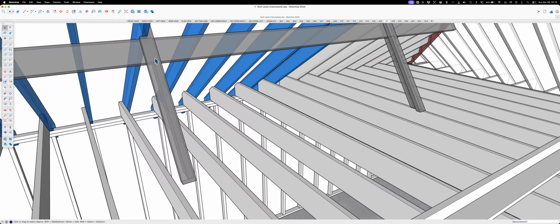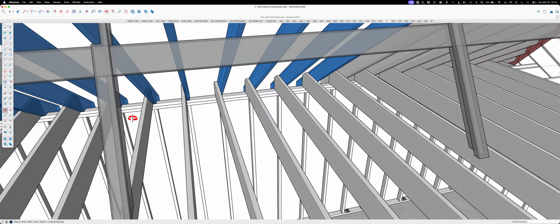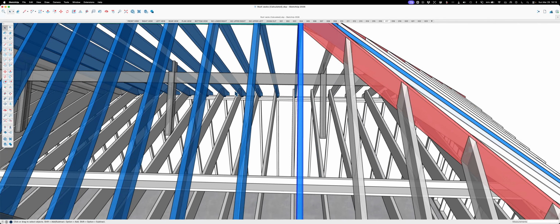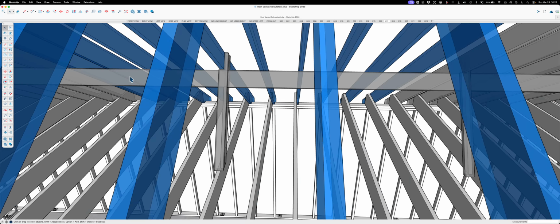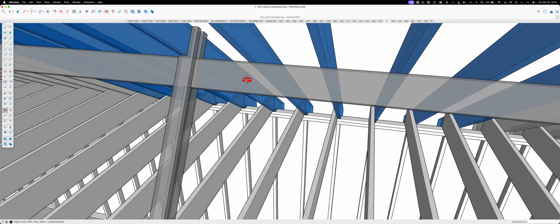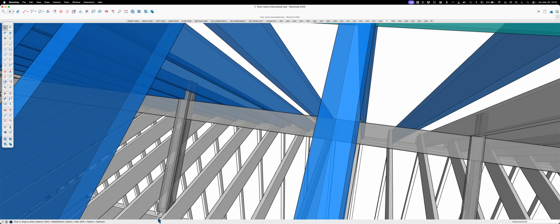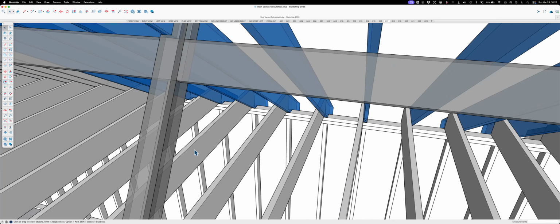I wanted to start doing it this way for a very simple reason. So I would measure down to the floor. First you hang the purlin, and the purlin has to be the same depth material as the rafters. So this is a 2x8 purlin. And you get a couple guys and you push the 1.5 inch edge up against the bottom of the rafters, and you toenail in a couple spots just to get it to stay so it won't move. And then you can eyeball down the face of this and find out where it lands on a wall, because there may be walls going front and back and stuff.